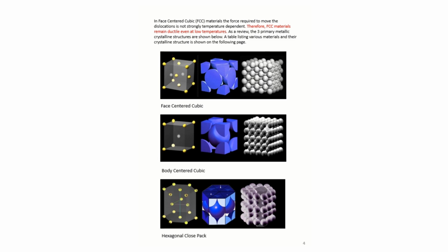Now in face-centered cubic materials, the force required to move the dislocations is not strongly temperature dependent. And so FCC materials remain ductile even at low temperatures, whereas BCC materials do have a significant change in their material properties based on temperature.